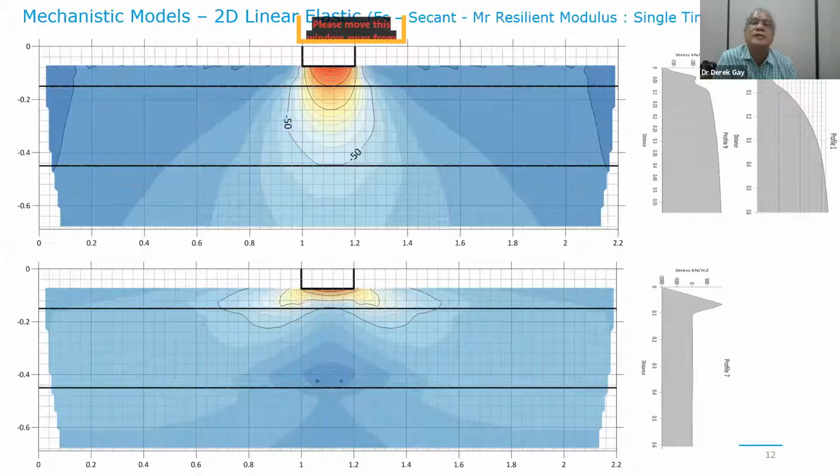as stiff as the base course, because when the asphalt cracks and you have alligator cracking, that is what occurs there. And the takeaway here is to see that when that happens, the stress transmits much deeper into the ground. If you see that minus 50 there, that stress goes all the way down to the edge of the base course into the subbase.